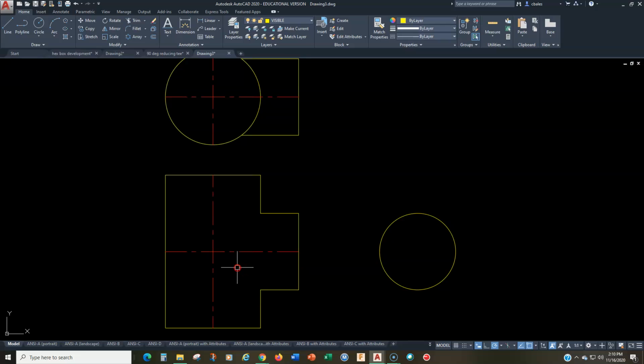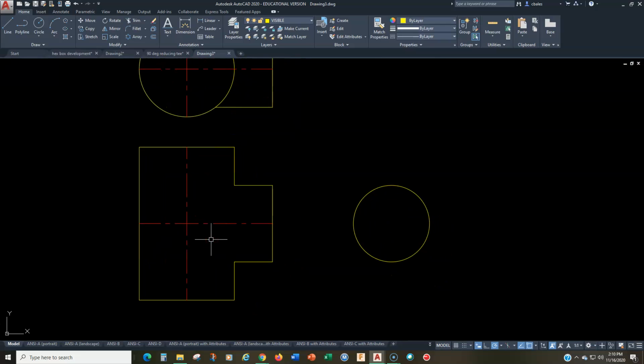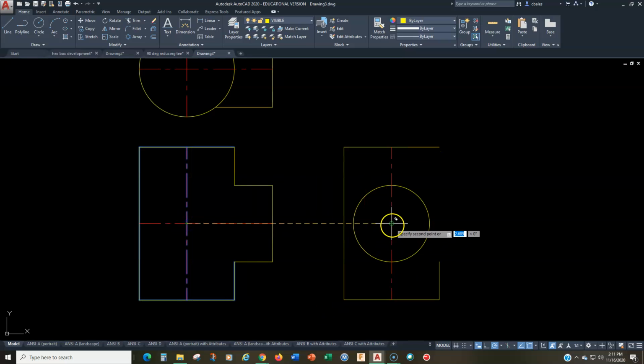Well, you know, I want to impress upon everybody the idea of reusing geometry that we've already drawn. Okay, so we've already drawn most of the view of the right side of this right here in the front view. So I'm going to copy this. Watch, I'm going to go to the copy command. I'm going to copy this line and one of these lines, okay? And I'm also going to copy this center mark. I don't have to, but I'm going to do that anyway. And then I'm going to move it from the base point here at the intersection to the center right there. All right? And then I can just use the extend command, and there we're done.